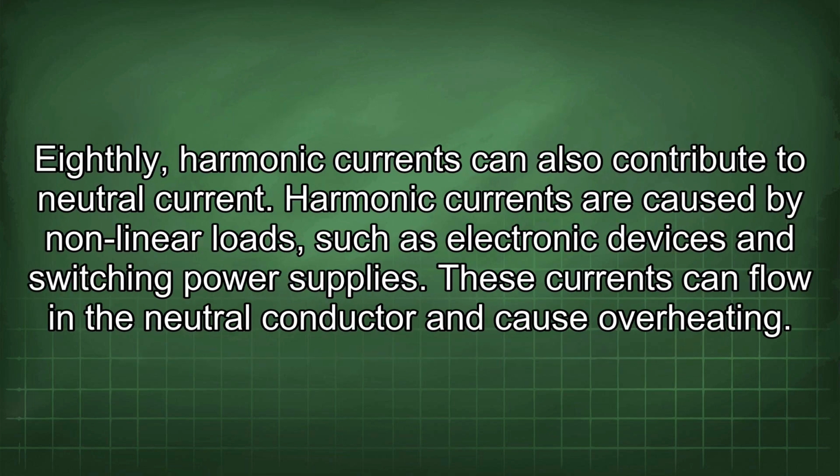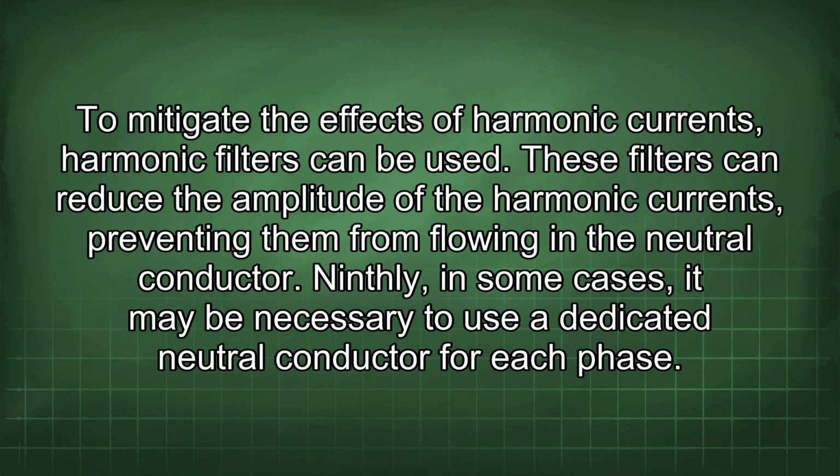Eighthly, harmonic currents can also contribute to neutral current. Harmonic currents are caused by nonlinear loads such as electronic devices and switching power supplies. These currents can flow in the neutral conductor and cause overheating. To mitigate the effects of harmonic currents, harmonic filters can be used. These filters can reduce the amplitude of the harmonic currents, preventing them from flowing in the neutral conductor.